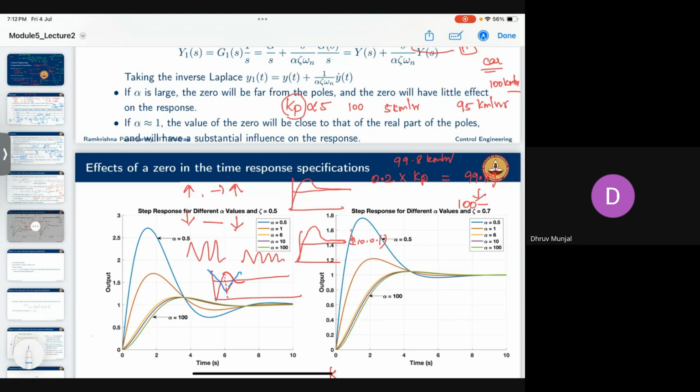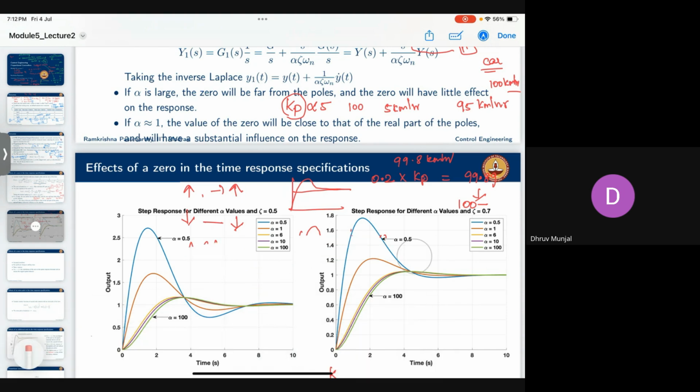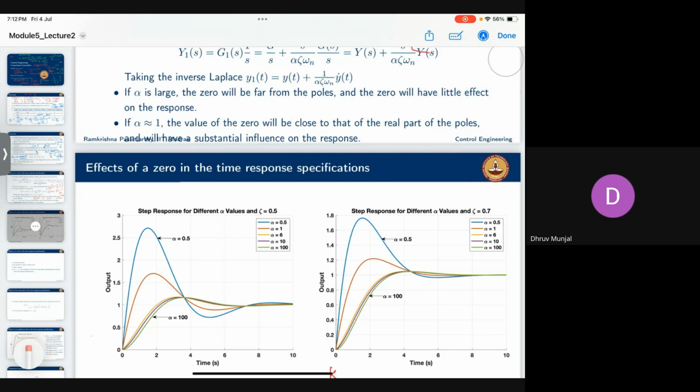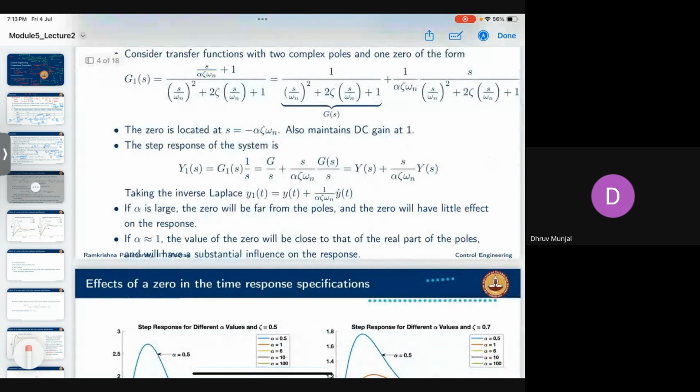Right. So that's it. The ultimate thing you can learn out of this is that choosing proportional, integral, and differentiable gains is a trial and error method. There are dedicated methods that you can study, but for simple systems, this would be helpful. Changing using trial and error would be helpful, but that affects the system behavior. So you have to be very careful while choosing these gains. You should know, based on the system's behavior, what kind of controller you want to design.